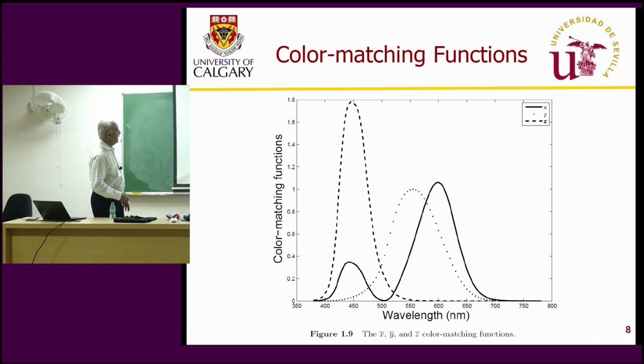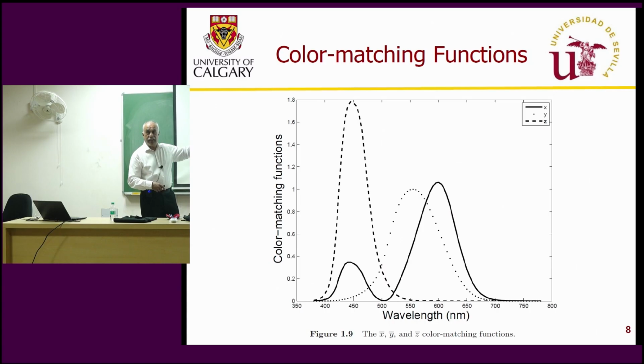So these are color matching functions in the XYZ domain. Now you take the projections onto these XYZ spectral functions, projections of the spectrum of your color signal. And then you get the XYZ components, like the Fourier coefficients or DCT, whatever. Okay? Projection is the dot product, or point-by-point product and addition, of your spectrum with one of these. You get the corresponding component.